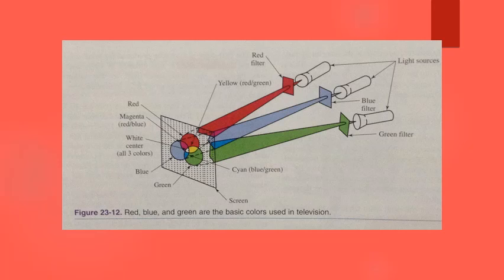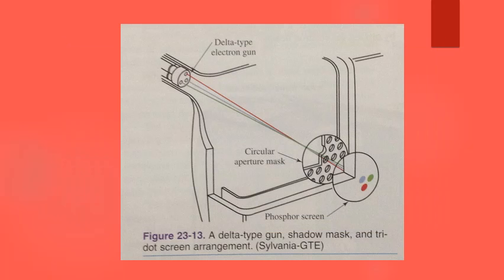The first color picture tube produced for retail sale was the Delta type tube. It was invented in 1950 and was basically the same tube used in the color television demonstration given by RCA Laboratories in Washington, D.C. The Delta type tube uses 3 electron guns placed in the neck assembly of the picture tube. The electrons are emitted by 3 guns toward the screen.